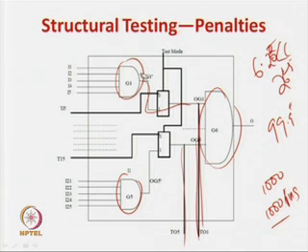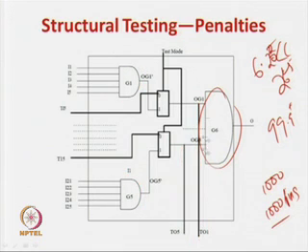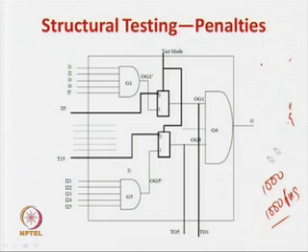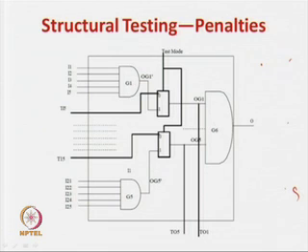you have to control these gates. Now you cannot observe this, right. So this gate is not directly controllable. Let us again go back to the original figure. So you can see, now somehow you have brought pins out and we can observe the value. But this gate is driving this AND gate. So I cannot apply any pattern over here directly. So there should be some extra arrangement so that I can somehow apply the pattern here.